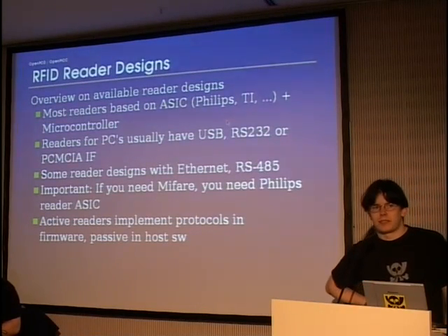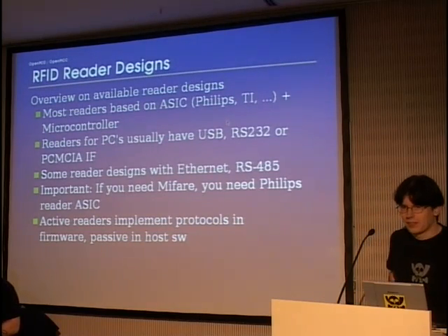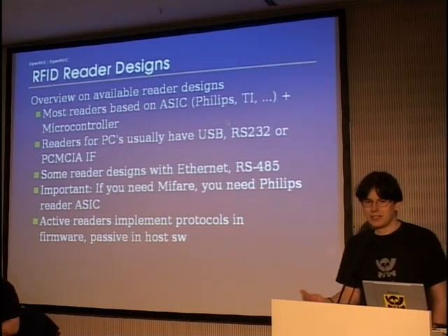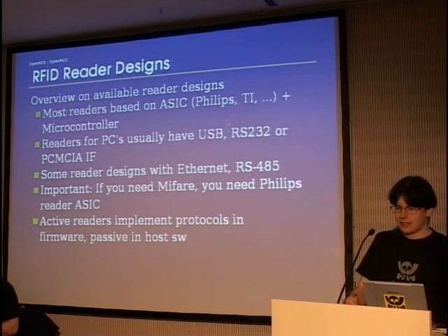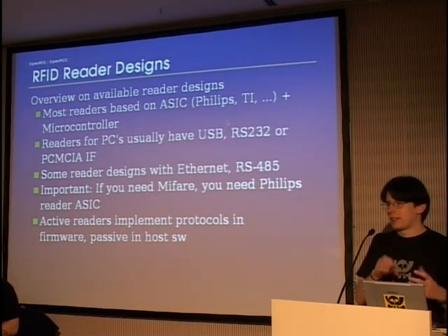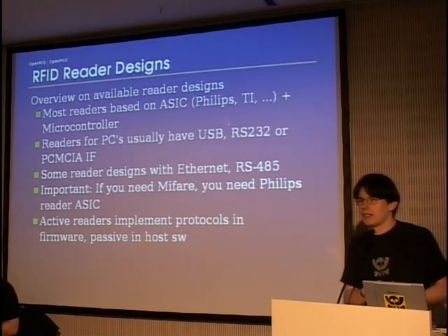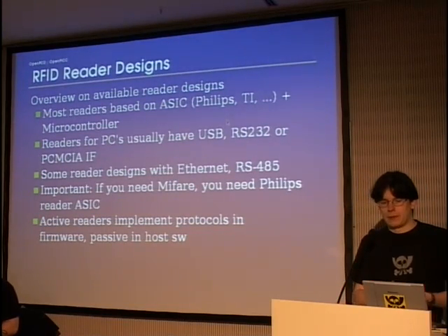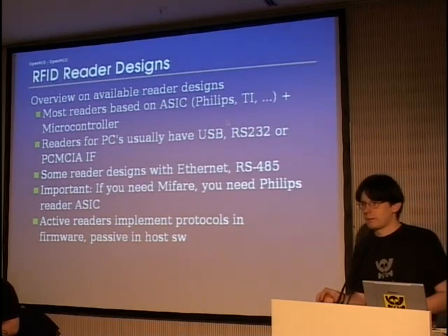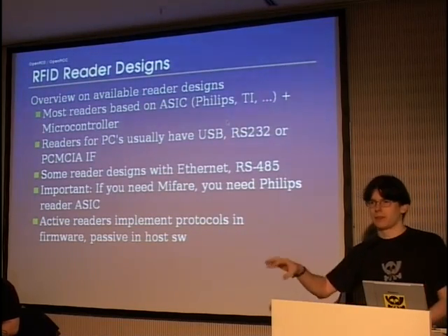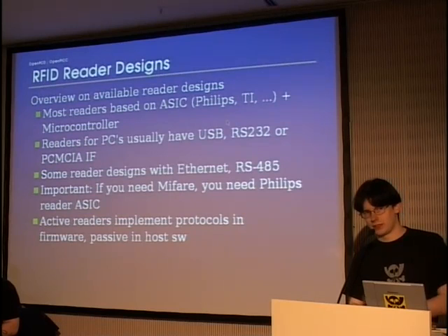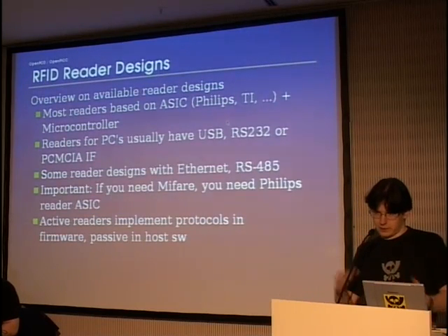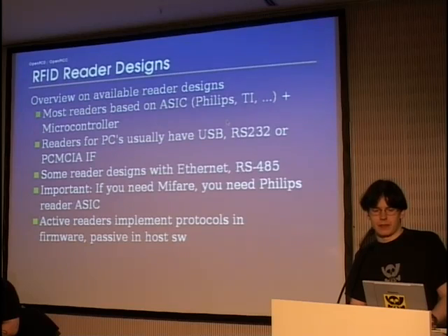There's basically two categories of readers. One of them is what I call active readers. The other one are passive. The active and passive terminology does not refer to the radio signal or anything like that, it's not about whether it's always actively emitting a field. It's just where the RFID stack runs, the actual protocol stack for the ISO 14443 protocol, for example. It can either run in the device firmware, so in the reader itself, the reader forming a sort of autonomous PCD side implementation of the ISO 14443 protocol, or the protocol can run on the host PC.